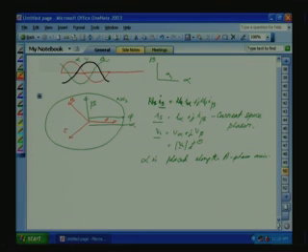So, let us take our Vs equal to Vs mod e raised to j omega t, because all these space phasors, the flux, current and voltage space vectors, rotate; the tip of the vector rotates with angular frequency omega t, that is the excitation frequency.